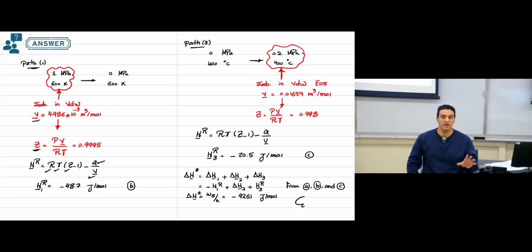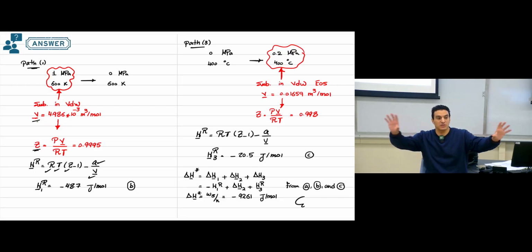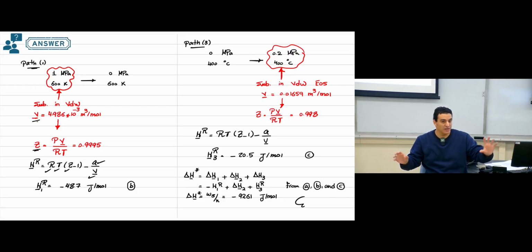Because at high pressure, the heat capacity is a function of pressure and temperature, and the thermodynamic model we have captures only the temperature effect on heat capacity. So how can we quantify the pressure effect? We need to make a hypothetical path. We will assume that the working fluid is not changing directly from the inlet to the final conditions, but through intermediate paths. So pressure will change to the ideal gas conditions, to vacuum. Then temperature will change at constant pressure, and then pressure will change again to the final condition. Then we will start to analyze each path.